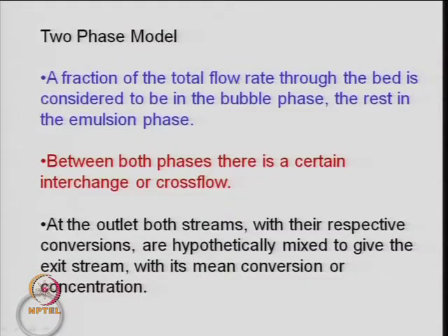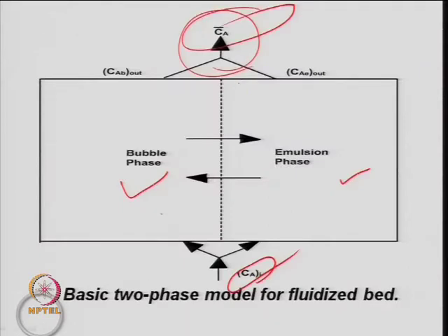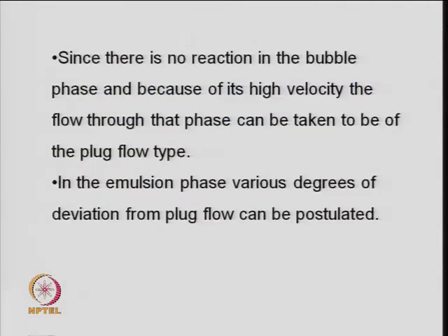It is a kind of mass transfer coefficient or overall transport coefficient, which can be determined experimentally or from the model. At the outlet, both streams with their respective conversions are hypothetically mixed to give the exit stream with its mean conversion or concentration. So, this is what I was discussing here. All these are discussed here.